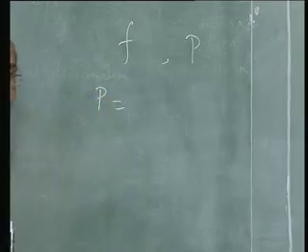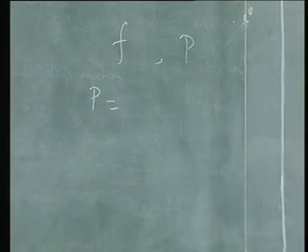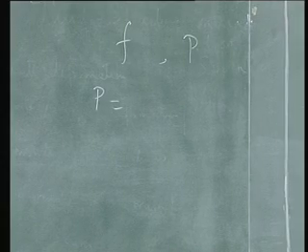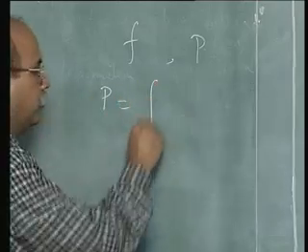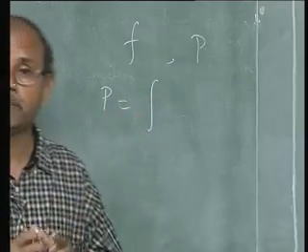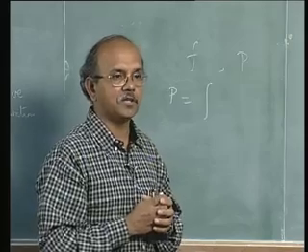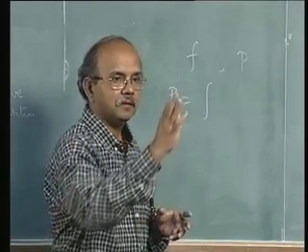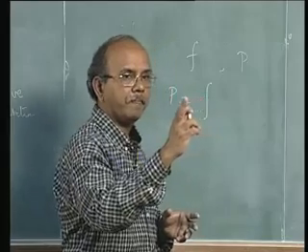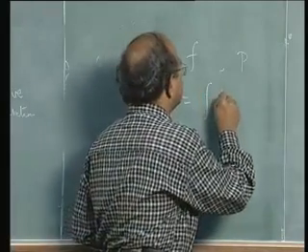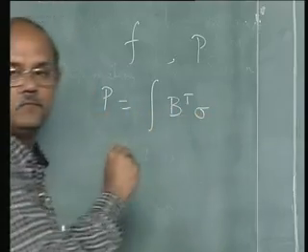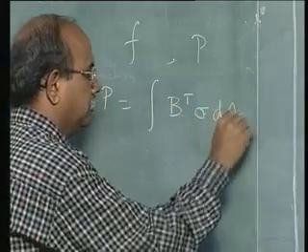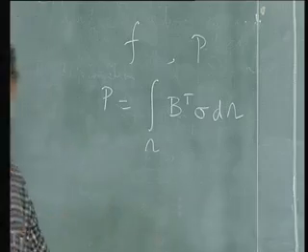We know from our earlier study that P, the internal force, can be written, from a finite element perspective, as the integral of B transpose sigma d omega, or dV or dA, whatever it is.